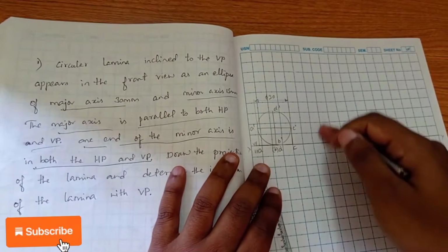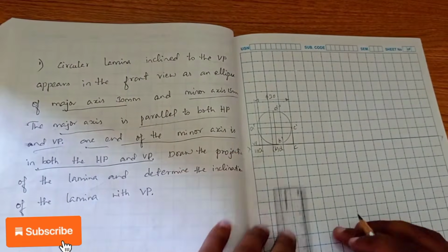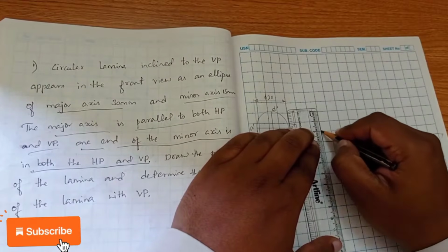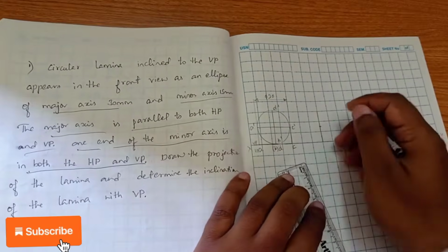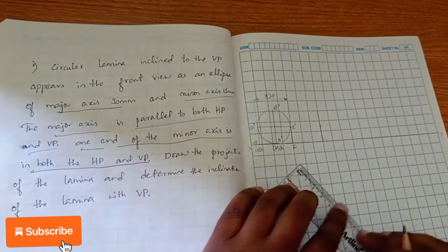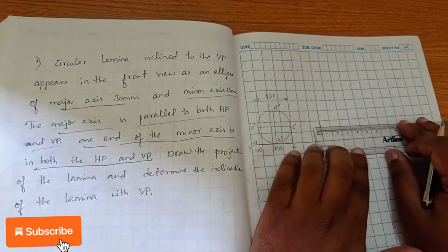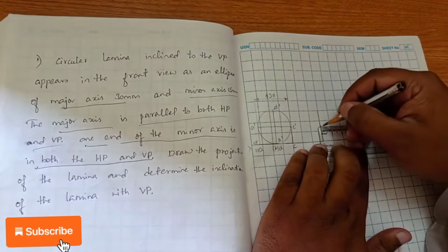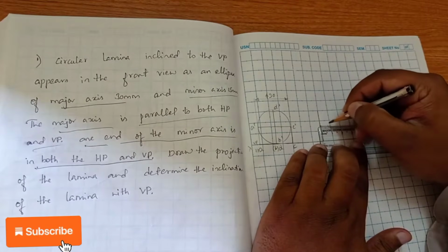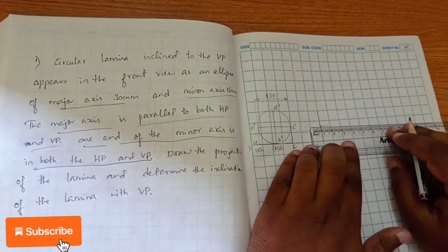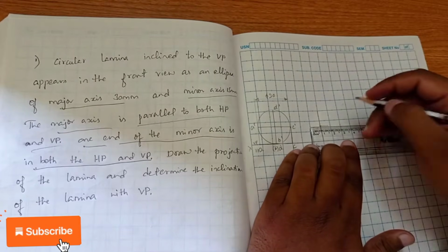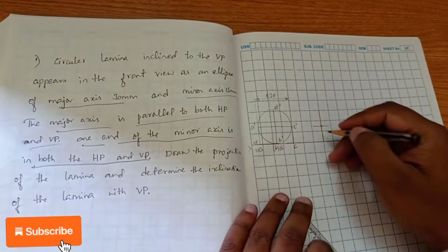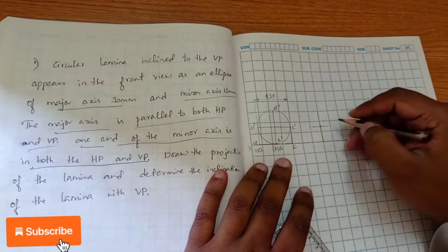Now we know that the second position will be an ellipse of major diameter 30. So I am drawing a major diameter of 30. Next, exactly from the center, we know that the minor axis is 15. 15 half is 7.5, so for 7.5 we have to end here. Marking at 7.5 on both sides. So you can see that these are the major axis and these are the minor axis. Now with respect to this we have to draw an ellipse here.